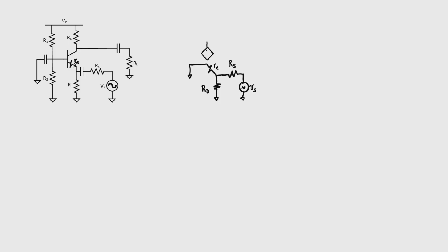The job of our transistor is to multiply the base current times beta and pull it down through the collector. I sub B is the current that flows through the base of the transistor. Attached to the collector, we have two resistors, R sub C and R sub L. I'm interested here in determining what our load voltage is relative to the source voltage.